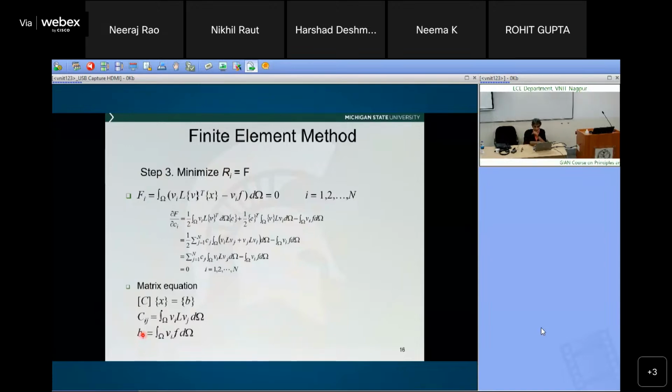There's no time variation involved, and for most of our models with just eddy current or flux leakage, this is enough, because with continuous excitation in eddy current, you just solve for the phasor, and once you get this E field, you can always multiply by e to the j omega t and get your time domain solution. But for a single frequency, there's really no time variation involved.